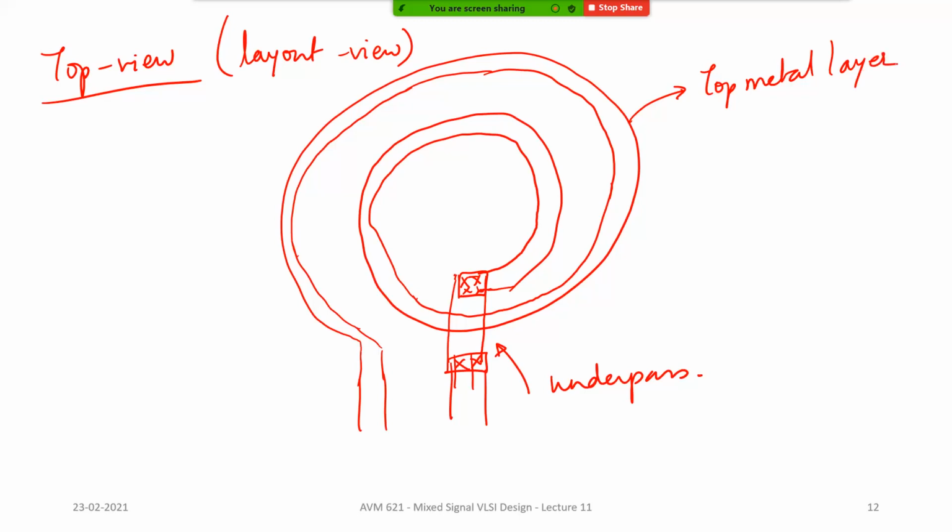In this process, we have an 8 metal layer process. There are other processes which have a little more, a little less. Whatever it is, usually inductors are done in the topmost metal layer, and just the underpass will be in the n-1 metal layer. Depending on the value of inductance that you need, there are some closed form equations which give you an approximate value. Usually these are properly simulated by running electromagnetic simulations, and that will give you the most accurate value of inductance and Q and other things.